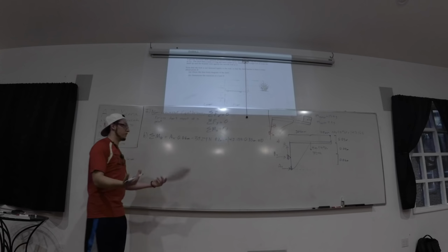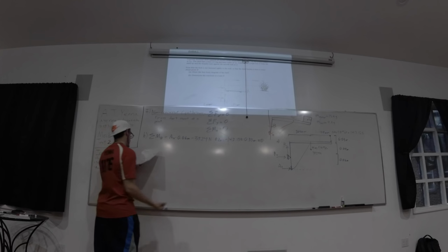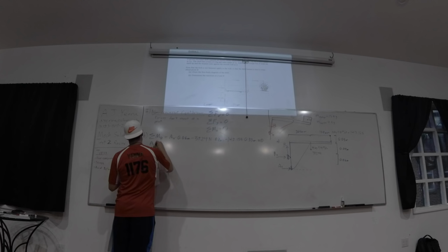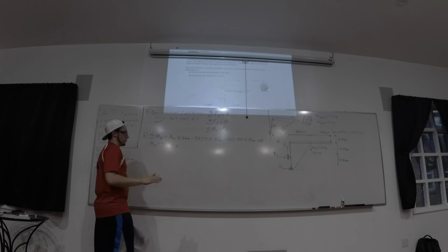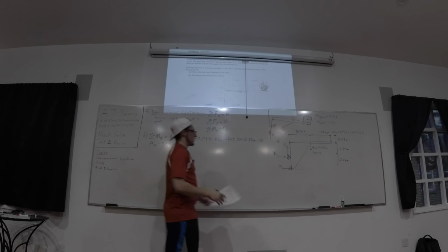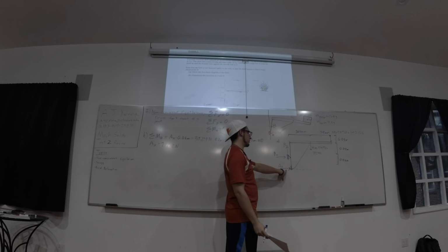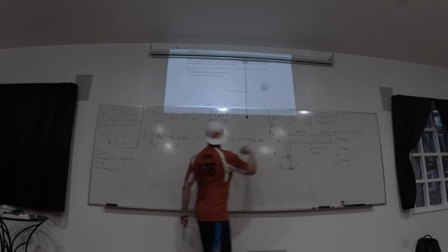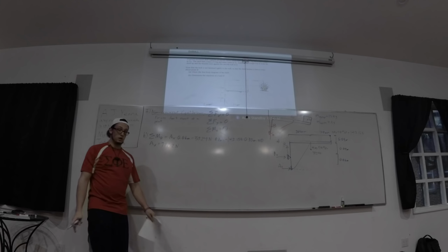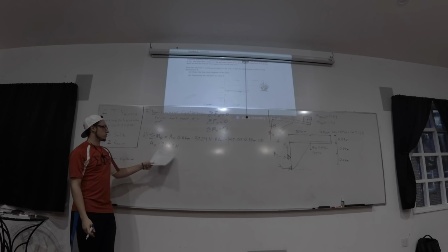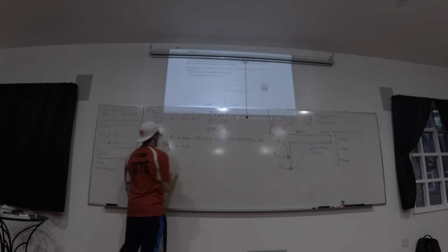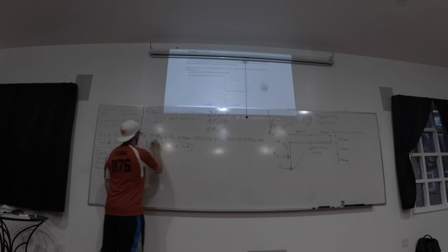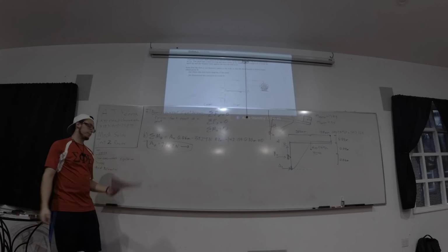So you'll all have calculators, do some math. Ax is equal to 989.2 newtons. And you're going to want to include what direction it's going in. So I originally denoted Ax as going to the right, and that's how I treated my signs when I plugged it into this equation. So since that was correct, and it came out positive, you're just going to agree that it is going to the right. And that's how you would notate it when you box your answer.